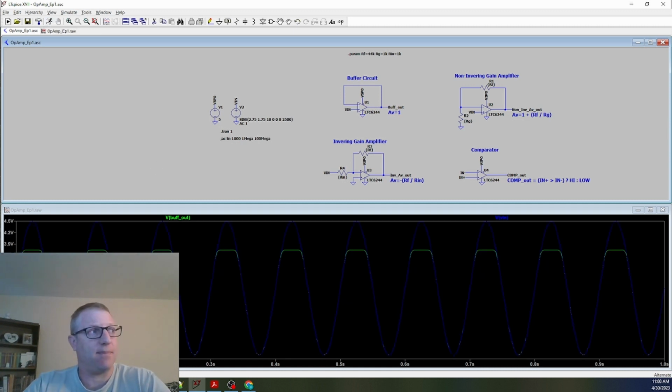So what do we see happening here? We can see that because our input exceeded the VCM, it was no longer doing what we were expecting it to do. Even though our input was going from 1 volt to 4.5 volts, just as expected, because we exceeded that 3.5 volt VCM, we could not get the output.